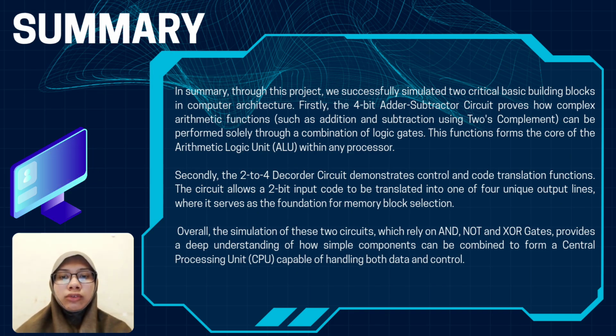In summary, through this project, we successfully simulated two critical basic building blocks in computer architecture. Firstly, the 4-bit adder-subtractor circuit proved how complex arithmetic functions such as addition and subtraction using 2's complement can be performed solely through a combination of logic gates. This function forms the core of the arithmetic logic unit within any processor.